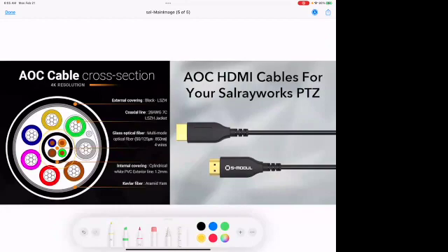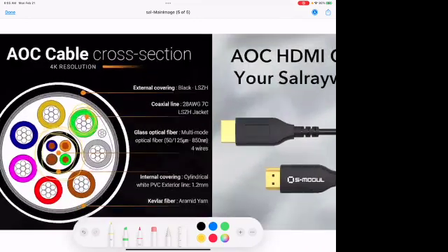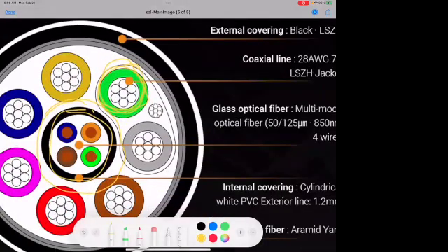So they keep them at a distance with some kind of a low dielectric material. And then they shield them around. This is at the center. But then look at this one. This one is a coaxial line. The only difference is that it has multiple center conductors, because this way you send multiple signals. If you were to take away all of these conductors here, to remove them for a moment, what you would have is exactly what we analyze. Now it's the next step, of course, not here, but there are design principles for these types of coaxials.